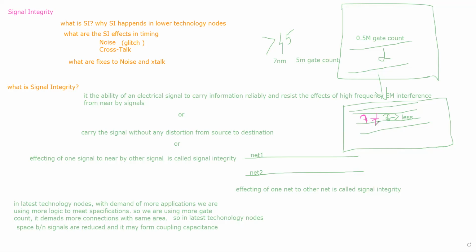Okay. See, you will have crosstalk or noise in both data and clock, but a clock is always switching. Data might be constant, sometimes it may change, but crosstalk will affect clock more because it is always switching. That we'll understand in detail. That's the reason we go for NDR rules and shielding for clock nets beforehand.